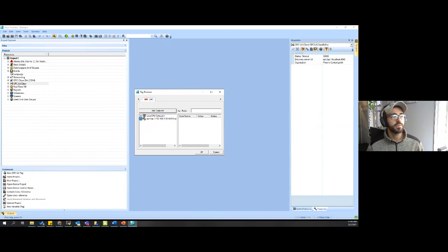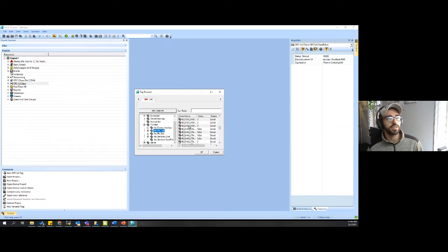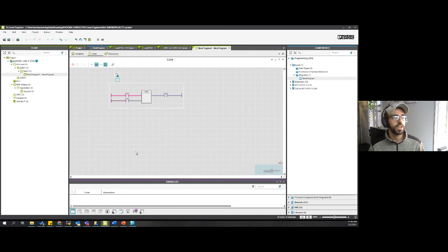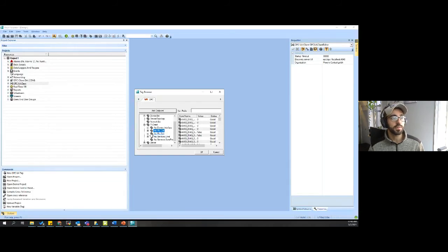You can drop the menu down and see all this information from the device. The tags are going to be under this PLCnext, under ERP. Here are your tags, and those actual IO tags are all global. If you want to find the tags we created, you have to find the name of your program under those drop-down menus.